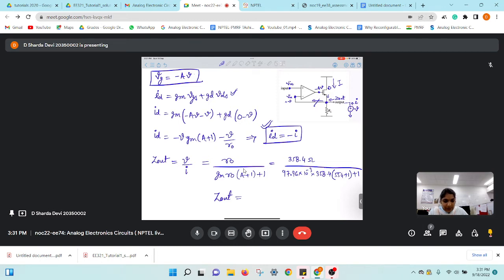Sure, ma'am. So we are actually trading off gain for stability of the circuit, right? Gain has always been a concern in the case of op-amps for stability reasons. Since open loop gain is so high, practically in the 10 to the power 4, 10 to the power 5 range, even if you get inputs in millivolts or a few microvolts, you'll see your output getting amplified to close to 1 volts, and mostly noise is a very minute value. Because of this high open loop gain, your output always saturates, so you are unable to use your circuit with that open loop op amp.